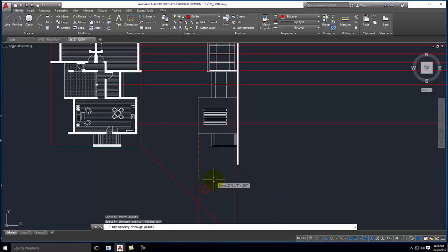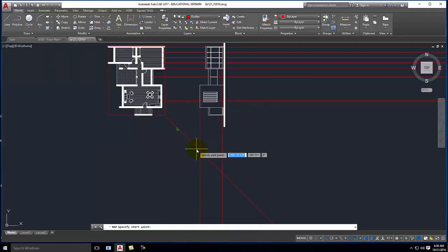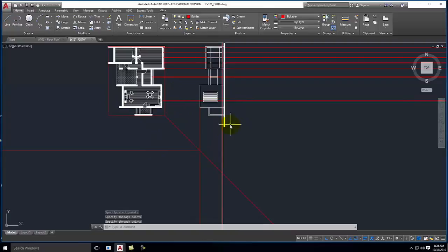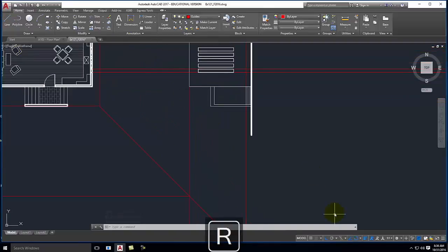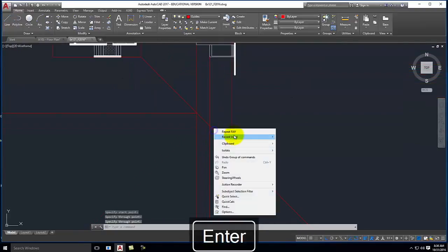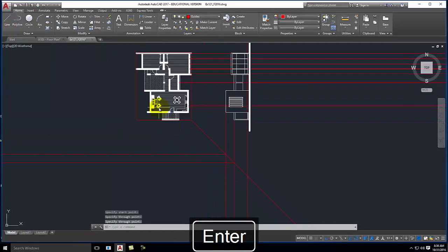So if I went down here and then across from where those two meet, that would be the height of this part of my building. Okay? Likewise, I could repeat the ray from that corner down and over, okay? And that gives me the height of the little pop out for the stairs.